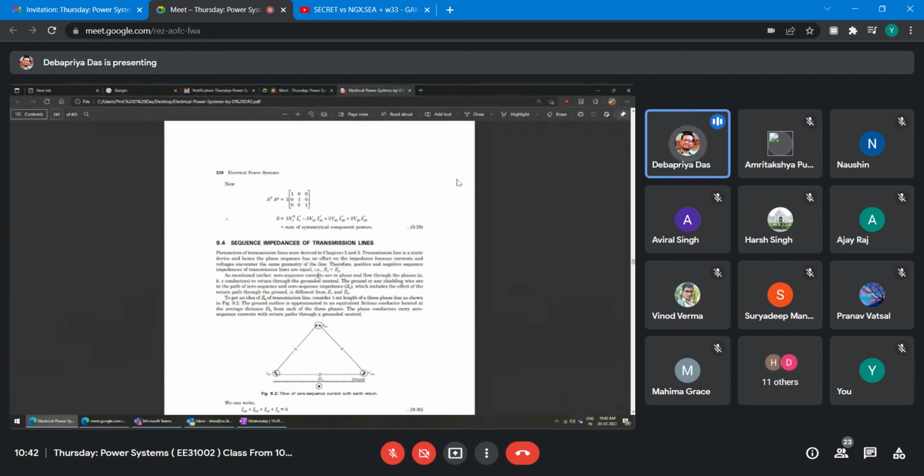That was a dummy parameter, right? No, during the iterative process, when you are writing the equations, the slack bus thing should not come in. So that won't even come into the equations, right? It will never come. And second thing, if the slack bus is changed, you need not bother about sigma and other things, right? I know this. That's why radial is given so that computation will be faster. In general, it is I is equal to YV.